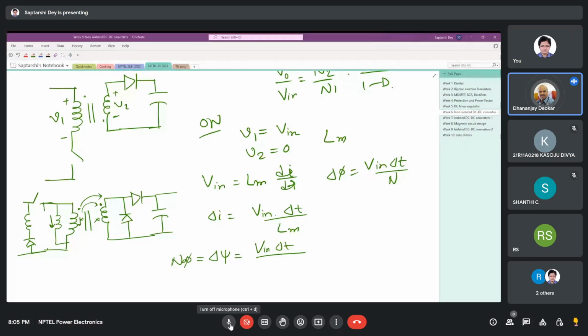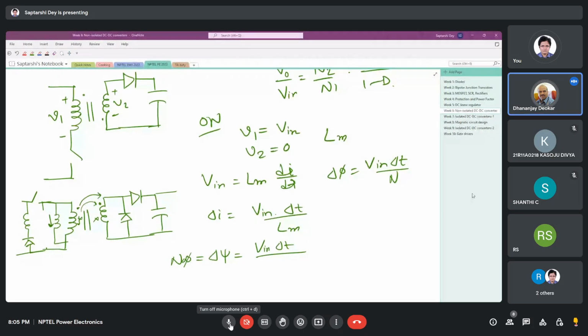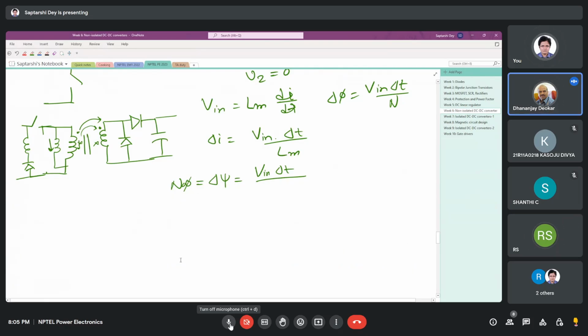Sir, this crossing diode inductor is flux reset. Yes. Then it is lossless core reset, something like that. We're not talking about loss in the core. We're talking about the stored energy in the core. We have to give it some path to go back. That's why it will dissipate with the L by R time constant if there is a resistance. Do not introduce resistance in series with the diode. It is not dissipated, it is given back to the source.